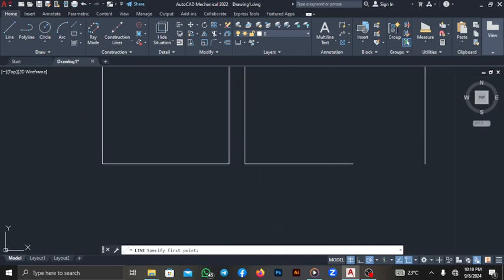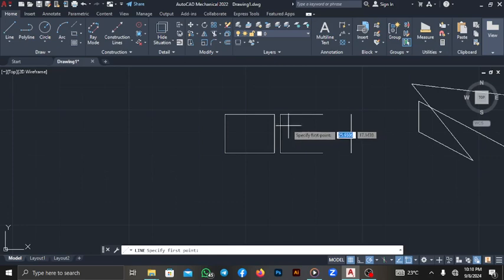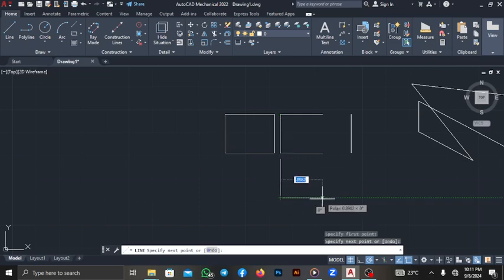All I'll do is that I'll place my cursor anywhere along a point on this line, maybe here, and then once I'm done I drag the cursor away, and then once you see this green plus indicated up there, bring the cursor down and then you see that the green line continues. So I click and then probably I drag it downwards. Now I want to have the same distance of the base, which is this side. All that I can do is get to the base point, the end, and then once the green plus is there I drag it down and then it aligns with it.